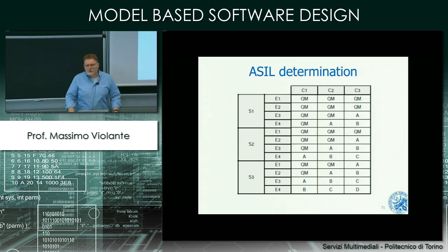So you will put at work a very long number of techniques to be compliant with the ISO26262, for example, for designing versus ASIL D. The end result of your product will be very safe, much more safer than what it is actually needed. This could be positive, but on the downside, your item will be much more expensive than what it could be. And this is very bad.